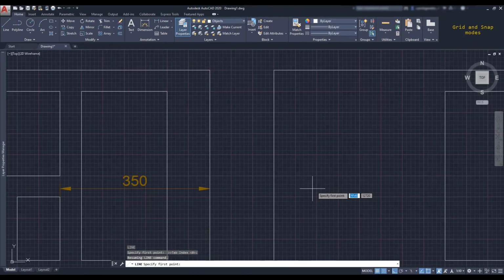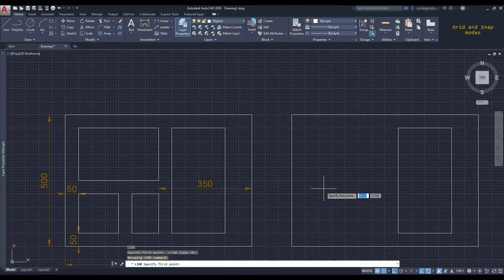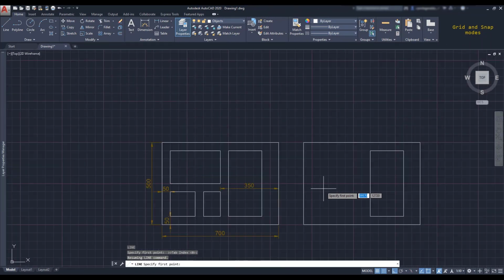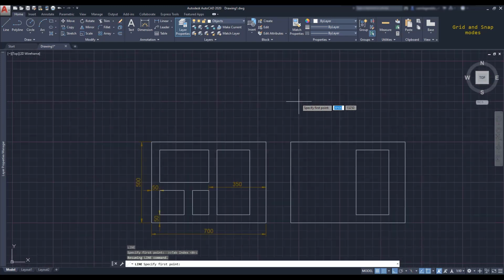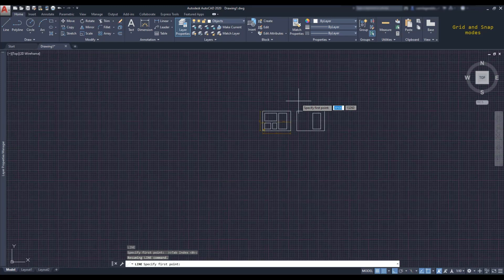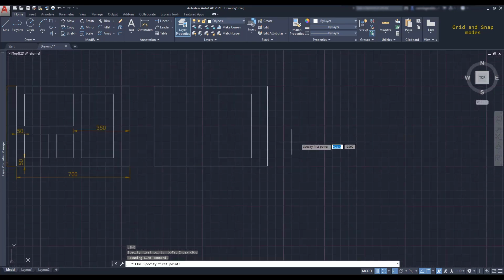If I'm zooming out the workspace, at one point the grid resizes in a way that the lines won't get that close. We couldn't see anything if that would happen. This means that at this moment the spacing here is not what we put in the settings. Be careful, don't draw anything now. Always draw in the maximum zoom. And in the case that you want to draw bigger objects, simple. Just change the spacing settings to bigger values.